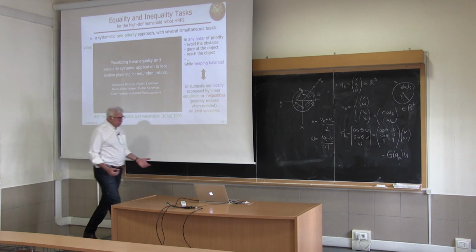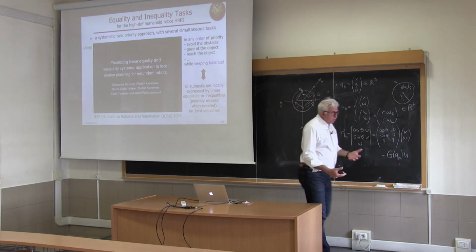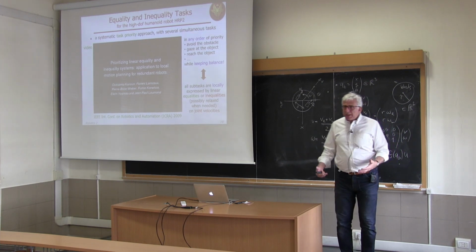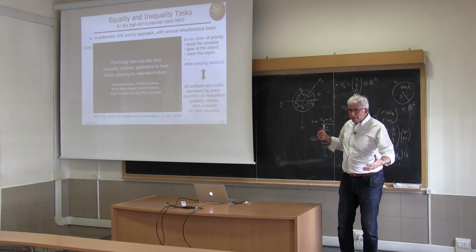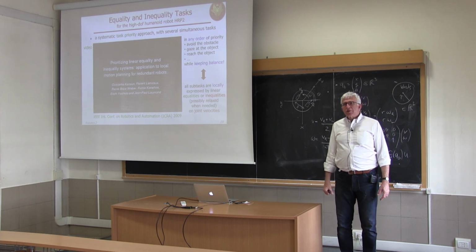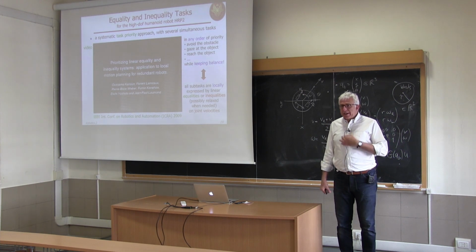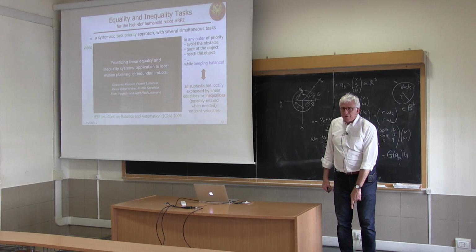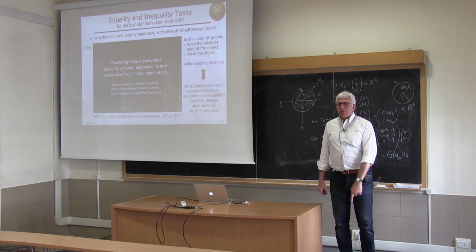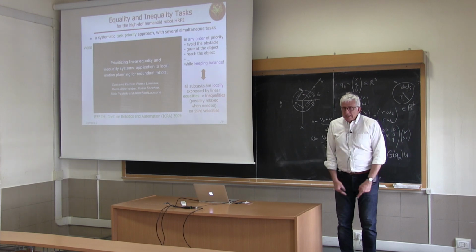And if we consider this as a completely static task, so that we don't move at fast speed, in fact, we can move, but without changing our supporting surface, then the balance is a constraint that says that the vertical passing through the center of mass of the humanoid body should fall in the supporting area. And you can imagine that this projection should stay in some area.